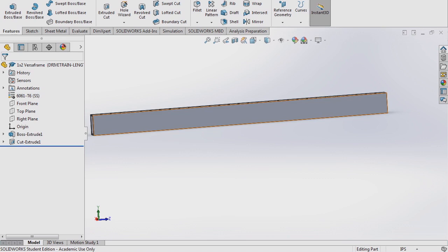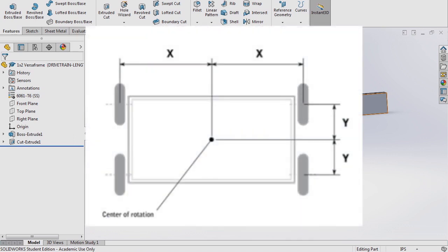By using this method, we're mimicking driving with a shorter drive base, which helps your robot turn easier. This is achieved through reducing the amount of turning scrub or resistance to the turning power of your wheels. How we reduce this is by, with our short drivetrain, reducing the distance to the center of rotation in the drivetrain.